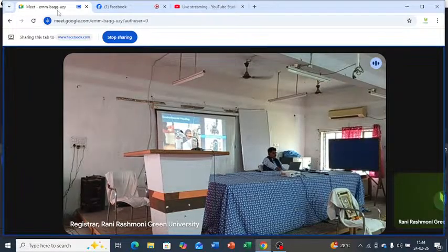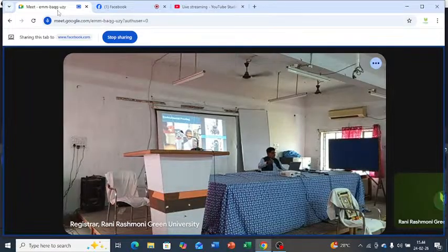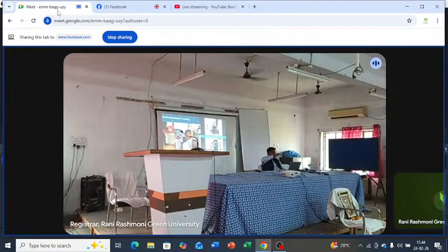Apart from that, there are the drop test, long distance baseline test, and cold chamber test, going down to minus 35 degrees. So if you have to take this total station and use it in Antarctica or somewhere the temperature is very low, it should give you the result. It is also tested under hot temperatures, over 60 degrees.